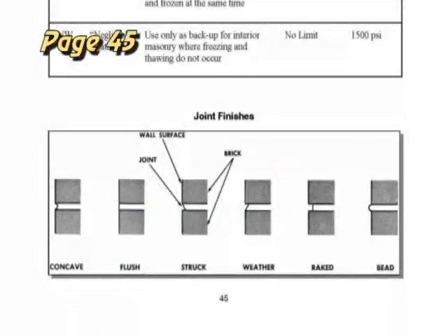And now we're talking about concrete masonry units, also known as CMUs, or simply sometimes as block or concrete block. For example, when masons get together, you'll hear them saying, well, I'm laying block today. That indicates they're laying these concrete blocks that are about 16 inches long, about 8 inches high, about 8 inches thick. That's the most common size. There's several different sizes, but that's what we're talking about here. Highlight that it measures 8 inches by 8 by 16. That's in the second sentence.